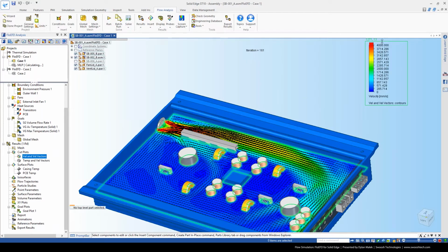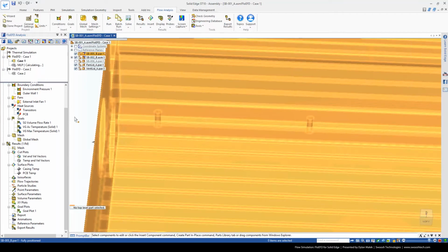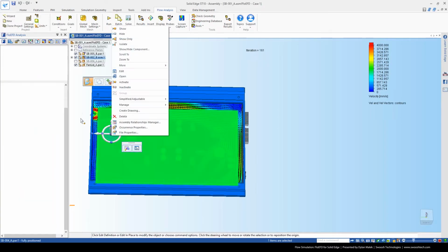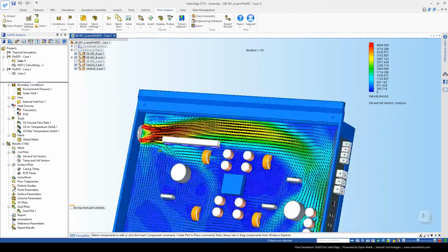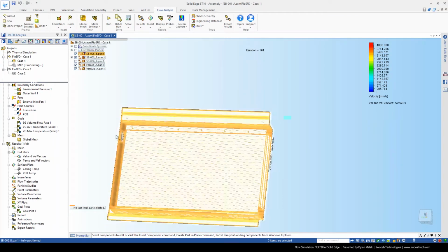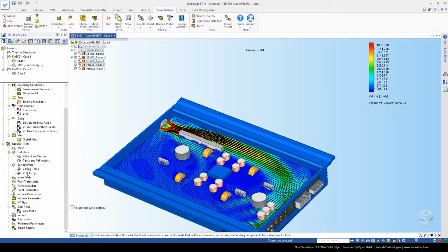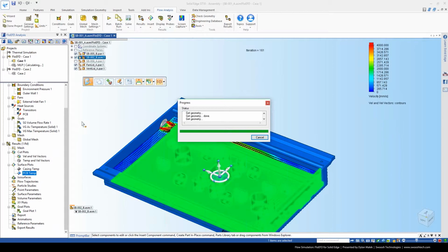And of course, this is the velocity one that we set up for the fan volume. And so again, this is not temperature, this is actually velocity. So there's the fan coming in. You can kind of see the airflow going around. Kind of missing going on the opposite side of that heat sink and kind of going around in the middle of the board. So again, that was the second thing we were kind of concerned about. Some temperatures here.